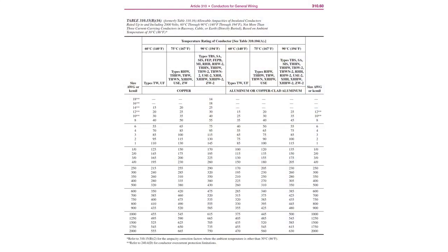One of the first things people do when they're doing an electrical installation is they learn or calculate the load that they have. So that's typically or commonly the place where people start. I have a 60 amp load. I go to table 310.15(B)(16) and I look up my 60 amp load.